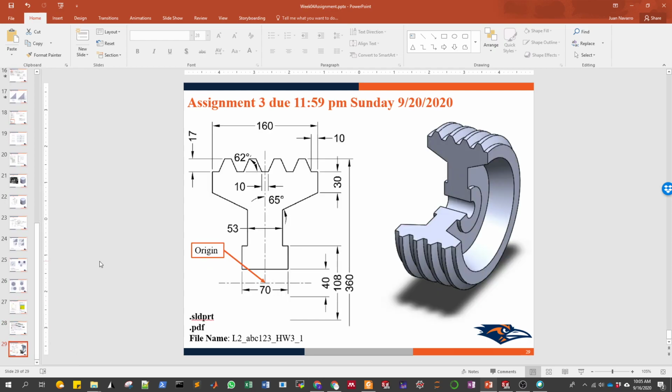And the homework is this. Basically, it is this profile of a pulley in a revolution. This is an eccentric revolution. It's the same as the quiz. But be careful, because this time I'm gonna verify the position of the origin. Check that I'm placing here the origin in the center. Here you will have to define several angles for these diagonal lines, all of these diagonal lines. And once you have this profile, you can use this line for construction in the bottom to do the revolution.